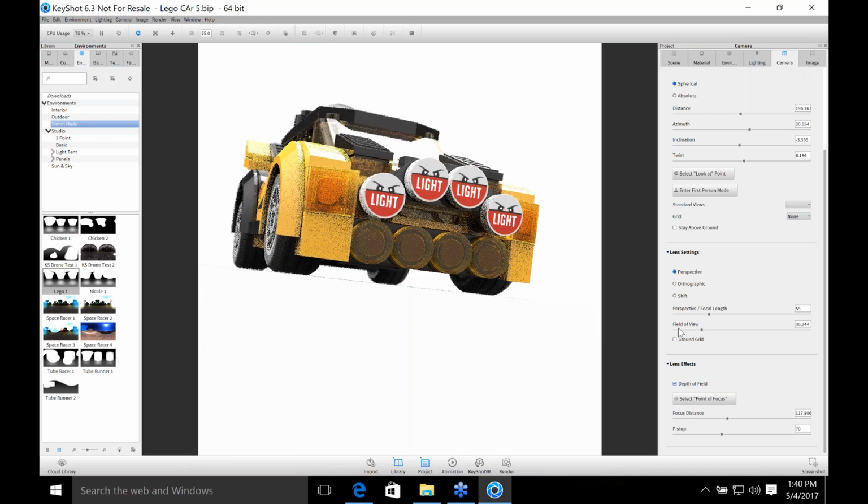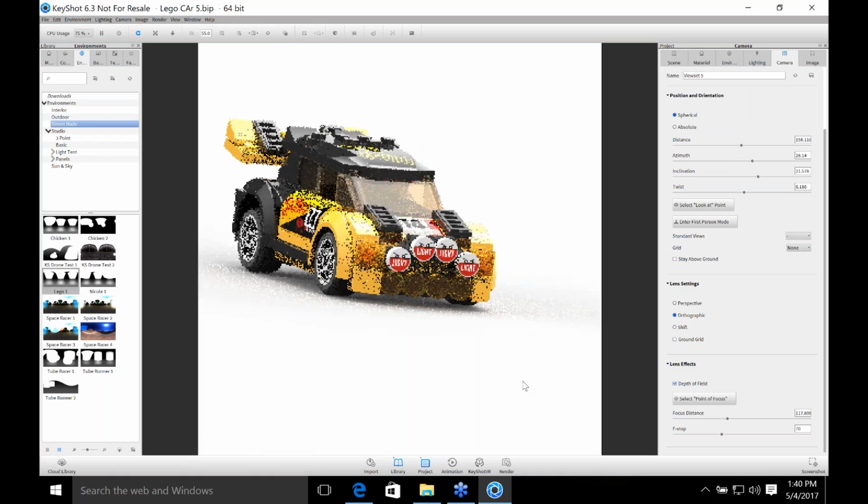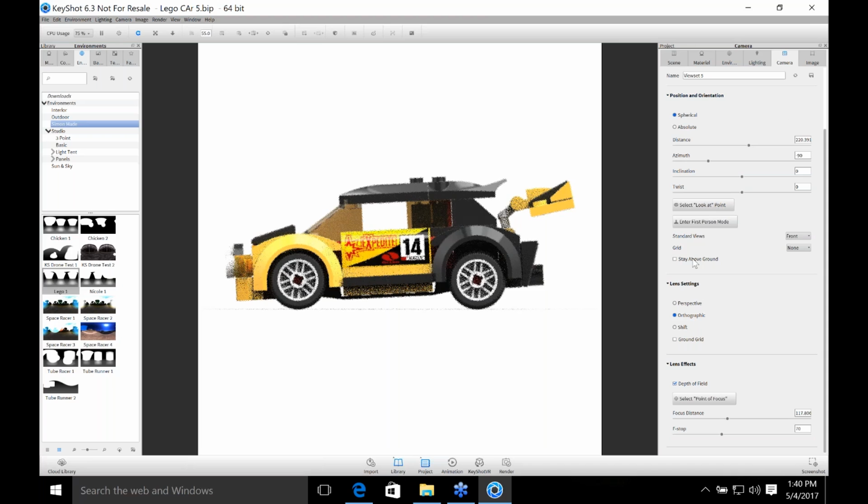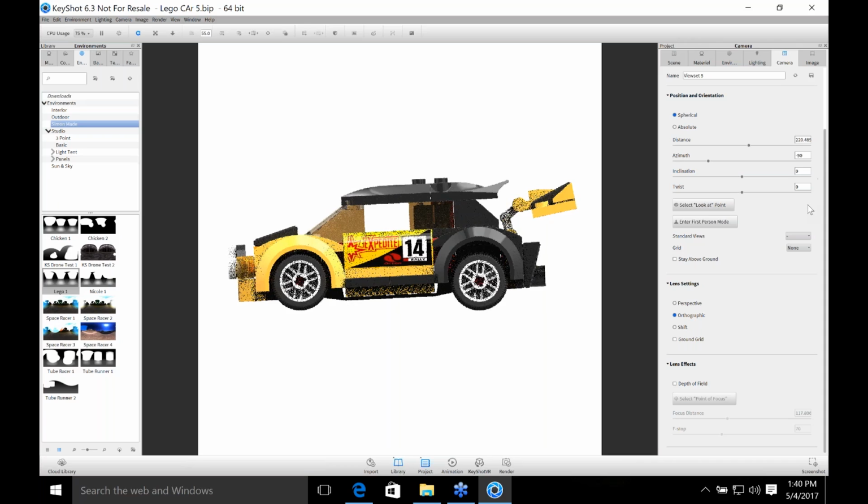In camera, there's one button down here that's for orthographic, which means we're going to get a non-distorted view of the model that you have. In this case, I'm going to look at the front view of this. I've got to go and take off the depth of field on that as well. So we're looking at this. It's a great exercise to go in and tilt that down just a smidgen to get a line underneath. Take a side view of whatever you're doing, an absolutely orthographic view of whatever you model, and try to make it pop off the page, off the background.